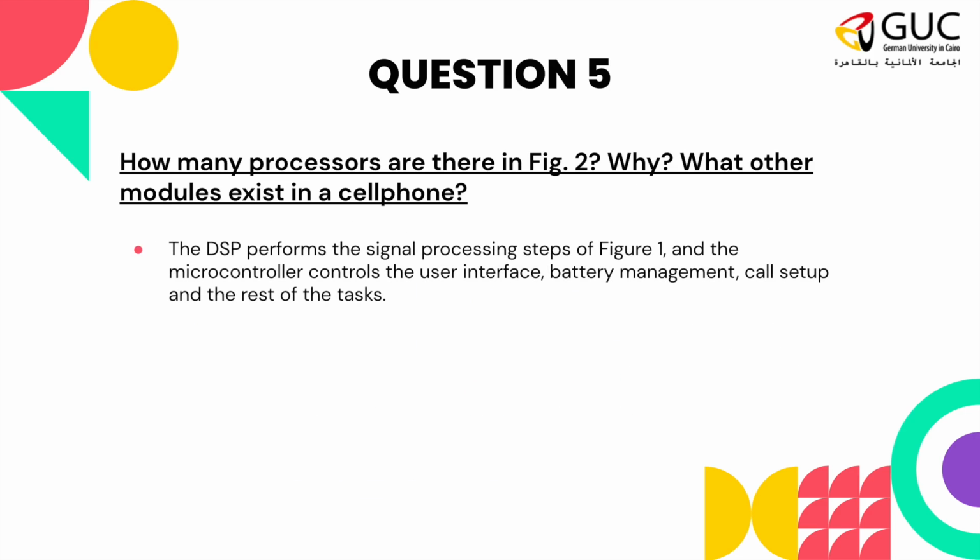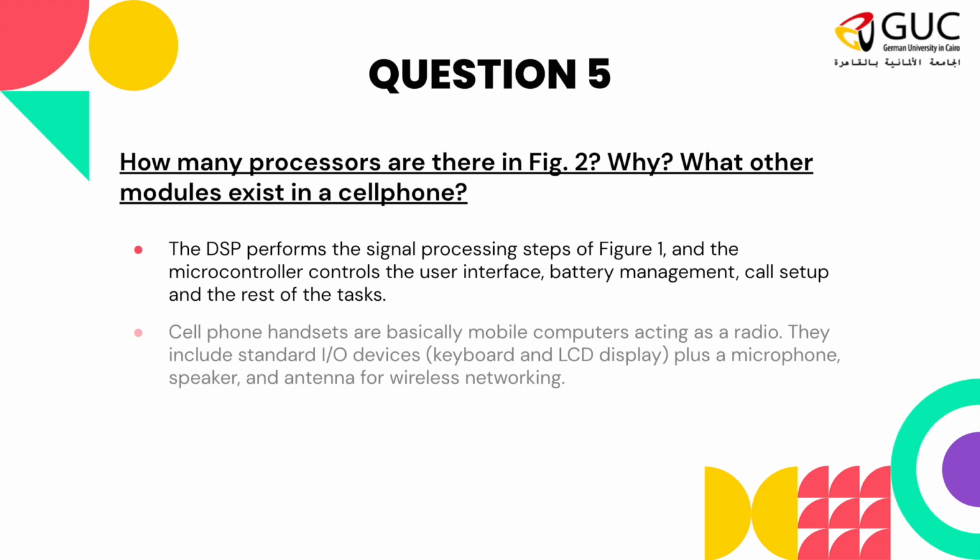So we go back, and the microcontroller controls the user interface, the battery management system, the call setup, and the rest of the tasks. So all other tasks that do not need any signal processing are done through the microcontroller. However, signal processing tasks are done inside the DSP.